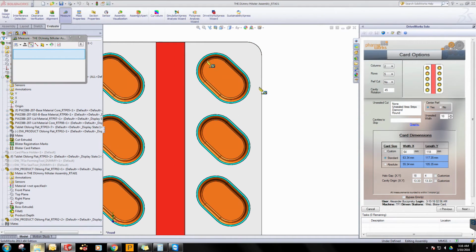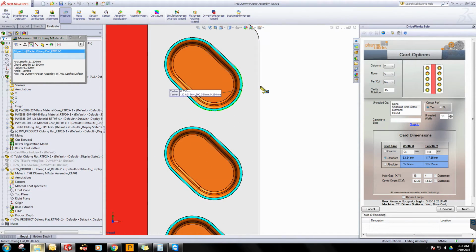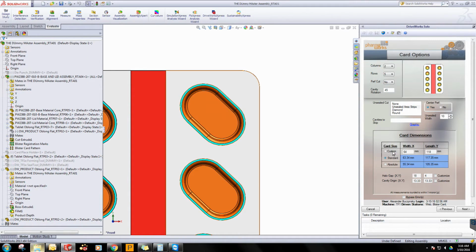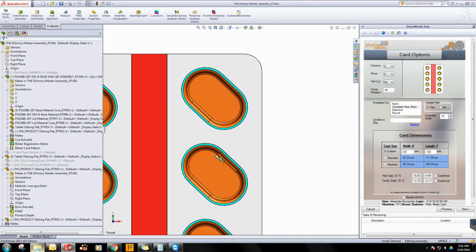So now the biggest thing that we should check is that there should be a 4 millimeter gap here, which it is. There's 4 millimeters there. That worked out. And just as a side note, this was a pain to program to get this to work with any angle that we have, but it's there. So now I'm going to go ahead and customize this. 65, let's make it 120. Alright, good. So that works.